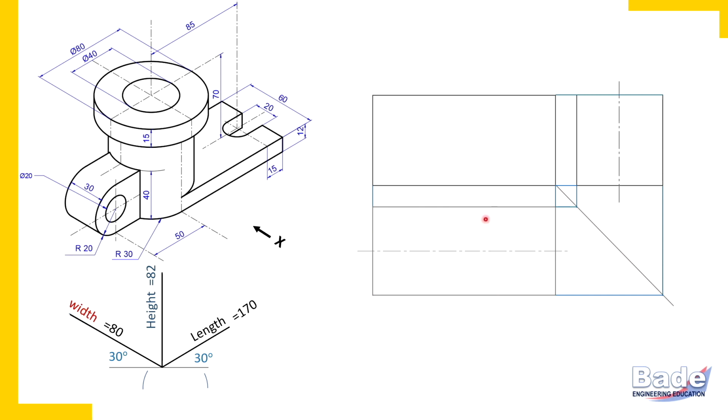And because these two sides are similar, we should draw the axis of symmetry in this manner, and the same axis of symmetry in the side view, to be projected using that 45 degrees line, or you can also draw that axis of symmetry independently. So let's proceed. Now I am drawing here this semi-cylinder.